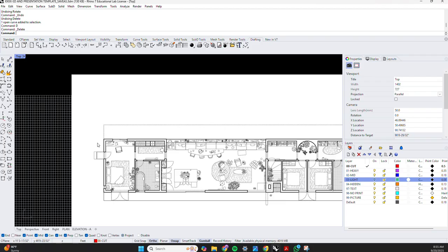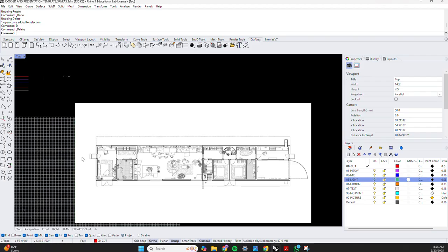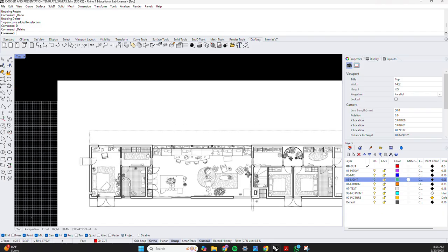You can take your whole drawing, or the overall exterior of the building is 120 feet or something. You can scale that known distance similar to how you would use a scale. It's not quite as exact, but as a starting point, that will work. The way I got to this one is based on my knowledge of the project. This is less exact than I would hope that you guys are working with, but just for clarity, I'm just going to do this example.